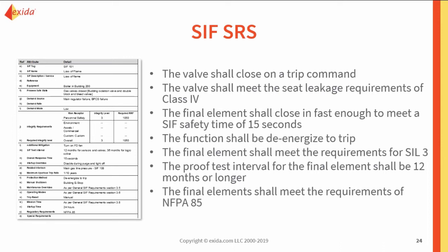Next, we want to look at how it's going to be plumbed, de-energized or energized to trip, the SIL requirements or the systematic requirements for all the devices in the SIF, proof testing, proof test coverage, proof test duration, proof test instructions, and any other requirements.